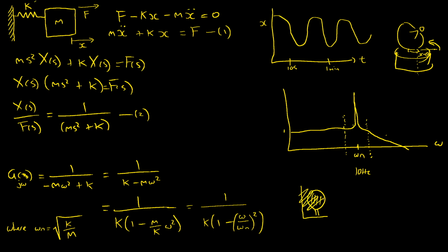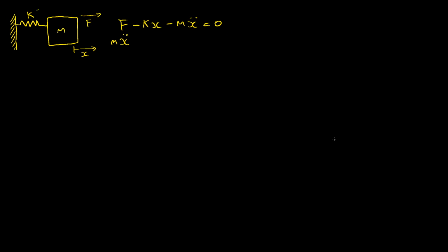But if you can't physically change your system, and you can't physically change the spring constant or the mass, our only option is to design a controller or a replacement for this F signal that controls the system the way we want and also changes this equation in the closed loop such that this peak is moved. So now let's consider the mechanical version of that, so changing the mirror mount. What might we do? Well, we might add dampening. And that's generally what changing the mount would do.